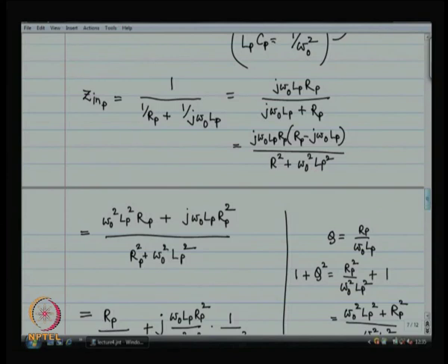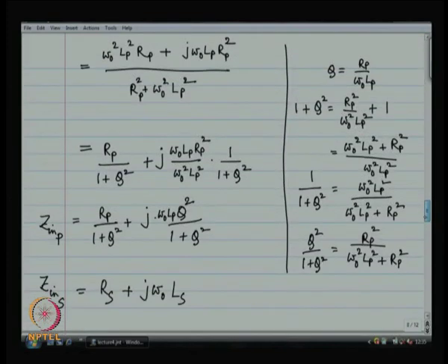place. The capacitor is useful only to visualize what q is going to be. The capacitor is useful only to use the appropriate formulae, otherwise the capacitor is meaningless. As far as this derivation goes, equating Z in parallel to Z in series, I have not used the capacitor at all. The presence of the capacitor is useful only for the definition of the Q.